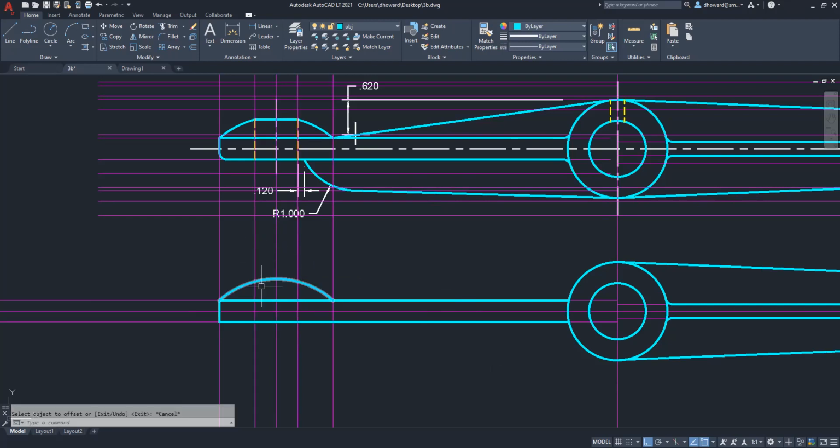Now imagine drilling that hole through and it would take out that little center portion. So I would connect these two lines here and then trim away that bit, leaving the flat that the hole would create in the side view. If you want to draw the outlines of that hole now, probably be a good time to do it. There they are. Imagine the hole going through it.